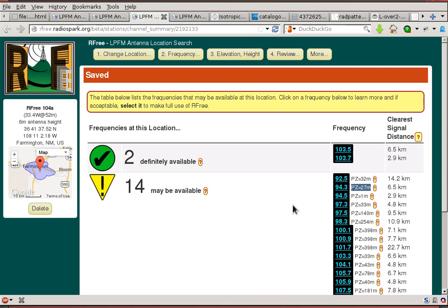So if you're in a location where you can raise the antenna, it's a good strategy. If you're in an urban area, you don't want to raise the antenna so far that the power goes below about 20 watts, but in most other areas you can raise that antenna. You'll get better line of sight, so you'll get a better signal anyway, and your prohibited zone goes down pretty fast because your power is going down.